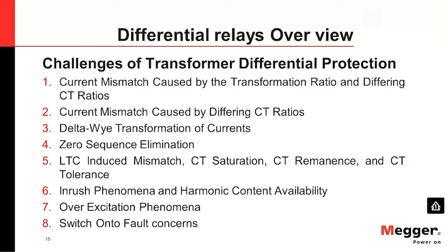Delta-Y connection, zero sequence, LTC even. When you have an on-load tap changer, you are making some changes, so is it going to affect or not? The harmonics, of course, are something we always have when we start the transformer. Overexcitation phenomenon, which comes from overvoltage in the network, and switch-on-to-fault function. So these are some of the functions which are affecting, and we have to take care of them during the engineering of the transformer protection, or let's say troubleshooting if we get a problem with the transformer differential relay.